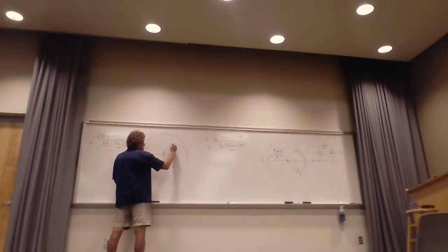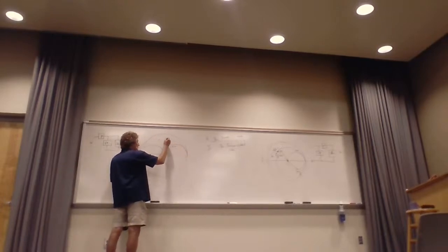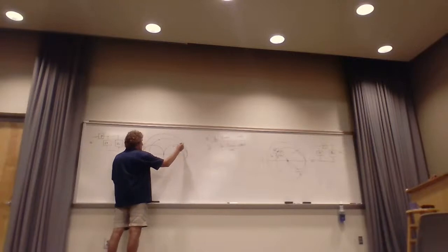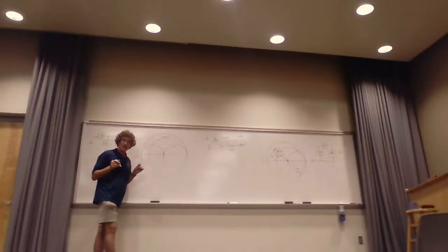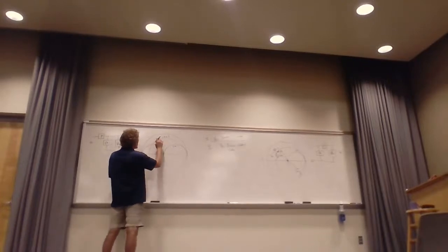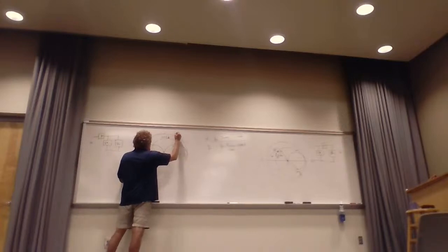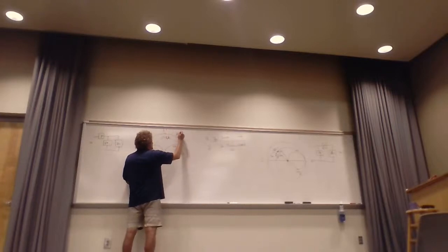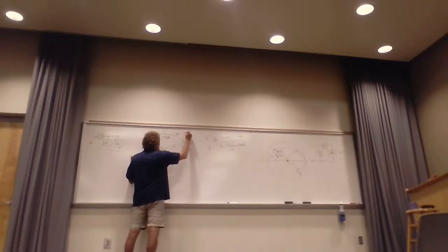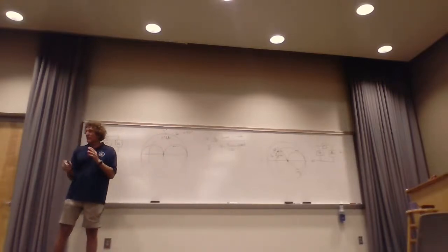All right, that's R equals 1. That's the rotated. Suppose I'm out here, and I'm going to try to show you the trajectory in one of these lines. Say it's R equals 0.3, and make it 0.3 j1. That's here. So my normalized impedance, because this is j1 right there, is going to be equal to 0.3 plus j1. Y'all follow me? Now, just follow me on this.